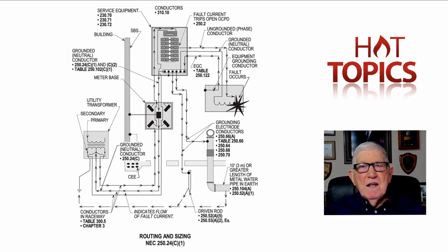Again, NFPA 70B for fuses, Chapter 18, for circuit breakers, Chapter 17, and the Annex L to 70B in the back of the 70B document kind of says, look at your circuit mapping. If this panel is just supplying more phase-to-phase loads without neutrals, then this neutral might be too small.